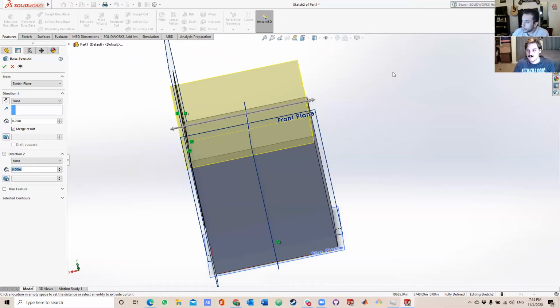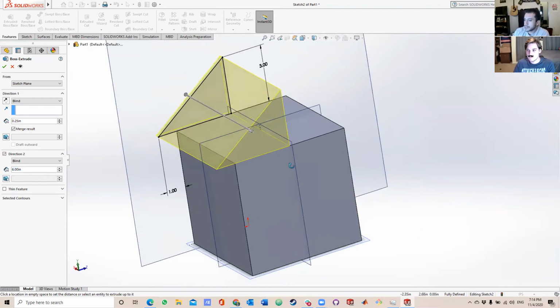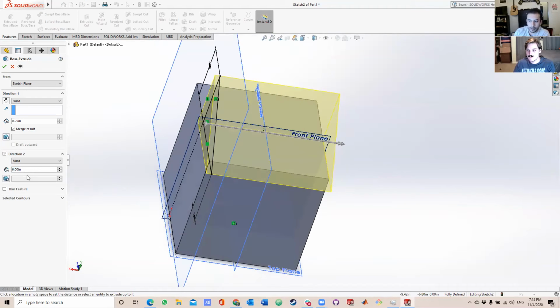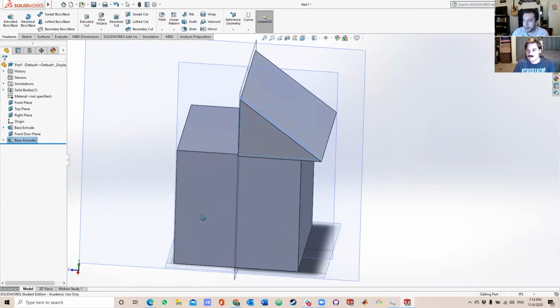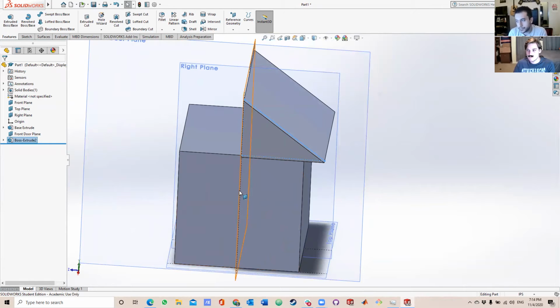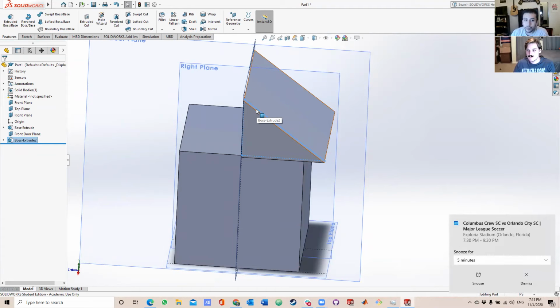So what we can do here is that we have this 6-inch extrusion, which has just become a kind of default. It wonders if we want that. So I'm going to make it 625 so I can have that bevel on both sides. And so I complete it. And here we have half the house. One of the things we could do is make another exact one on that same line and split the house across. But instead, what we can do is